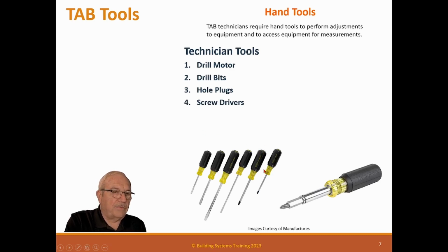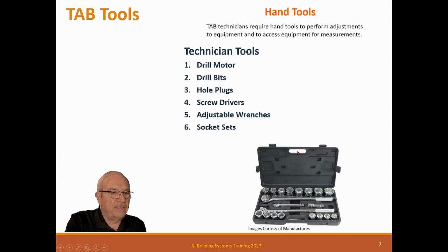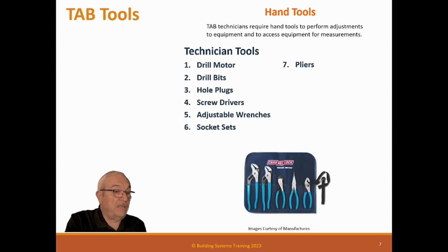You'll need screwdrivers, different kinds of screwdrivers. You'll need adjustable wrenches, and you'll need a socket set. The reason you need all this is if you have to adjust fans, you may have to adjust the fan belt, you may have to move a motor, you may have to do some of that kind of thing to get the balance where it needs to be. And you'll need to take covers off equipment to be able to get to stuff.